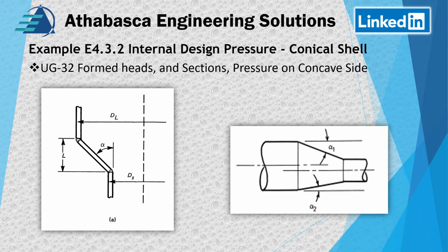But basically what they're saying, and this is in Section 8 Division 1 and 2, is if you have an off-center axis, then you take the maximum of alpha 1 or alpha 2, which makes sense because you're looking at the most severe case. And this is designing by rules. So there's a limitation on what you can do, but basically that's the approach with design by rules.